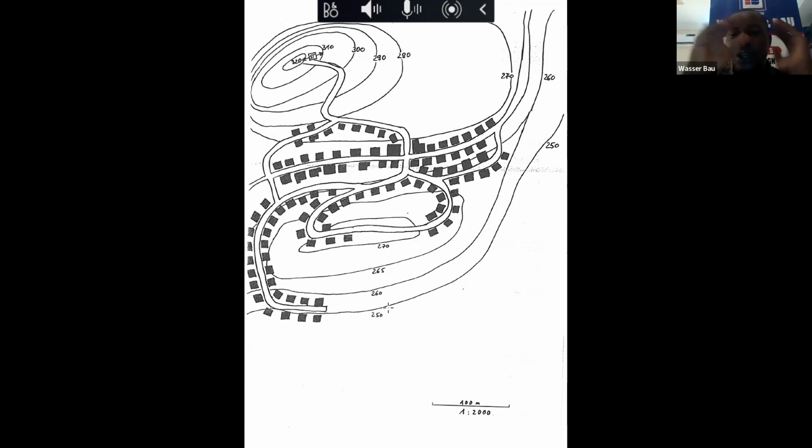Remember, there are 3 losses. Losses due to height, which is the potential term, ρgh. If you remember our Bernoulli equation, there are 3 terms. Losses due to change in geodetic height: I'm at 2 meters height, you are at 1 meter height. The height difference between the two of us is 1 meter, so automatically, 1 meter equivalent of pressure is my pressure ahead of you. Then you have the momentum flow. As water flows inside a pipe, there's a change in momentum, which is based on velocity, V squared over 2g. Remember our university days. Then the last one is the one based on H.